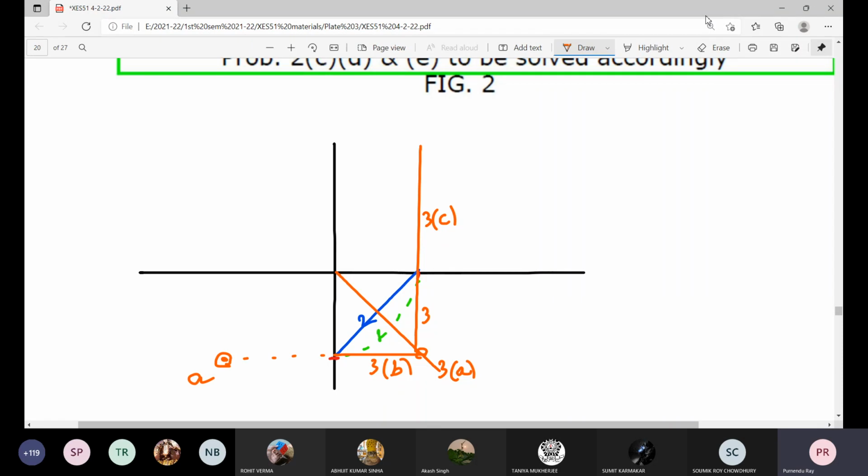Now, benefit of this third alternative is that only thing you need to draw a series of horizontal lines and a series of vertical lines. What is very easily can be done through the set squares. For first one, this green line, you need to draw a circle where from this center, it's sure that the needle of that compass will pierce that paper through and make a hole there.